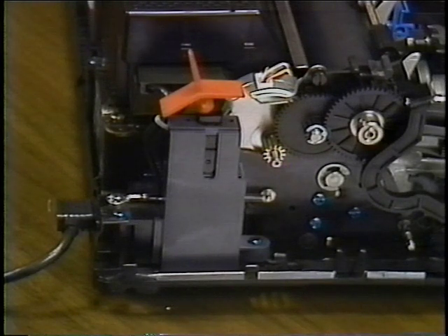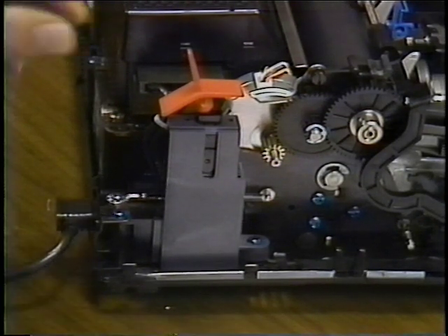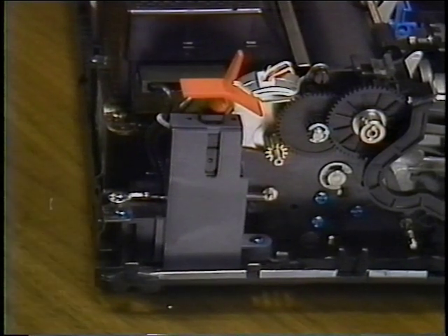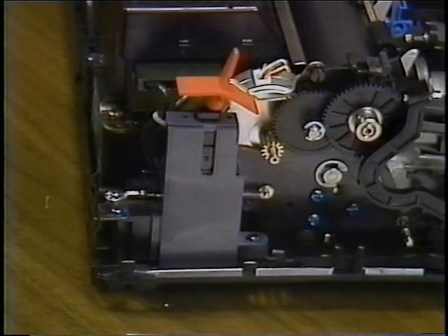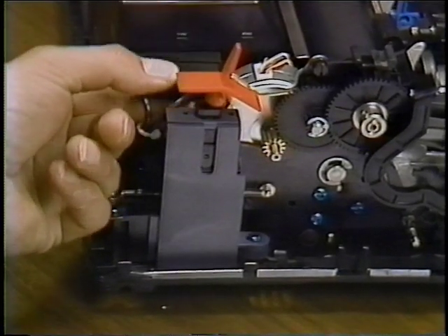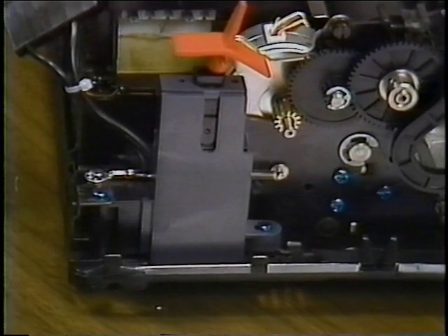The third fuse is in the on-off switch trough. In order to get at this fuse, the on-off switch trough must be removed. To remove the on-off switch trough, be sure the switch is off, then unplug the line cord from the back of the machine. Next, unplug the transformer connector. Remove the 3 on-off switch mounting screws.